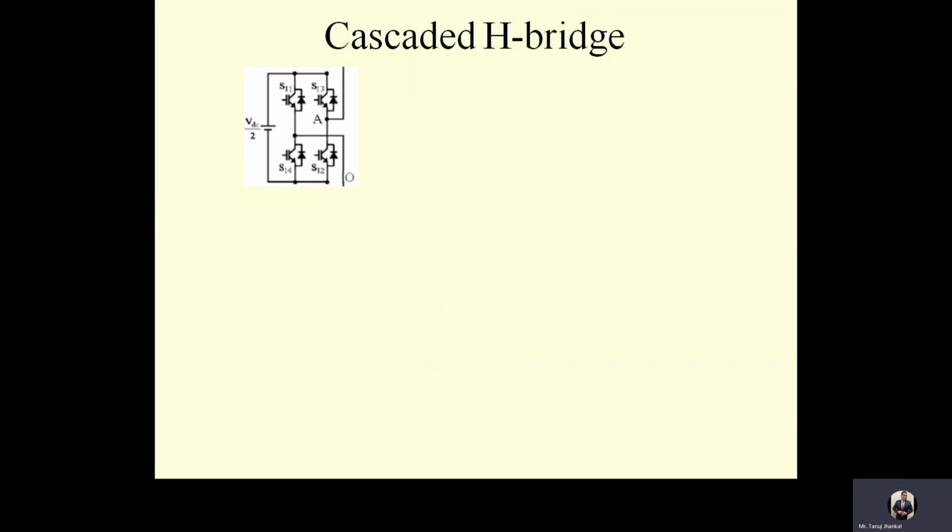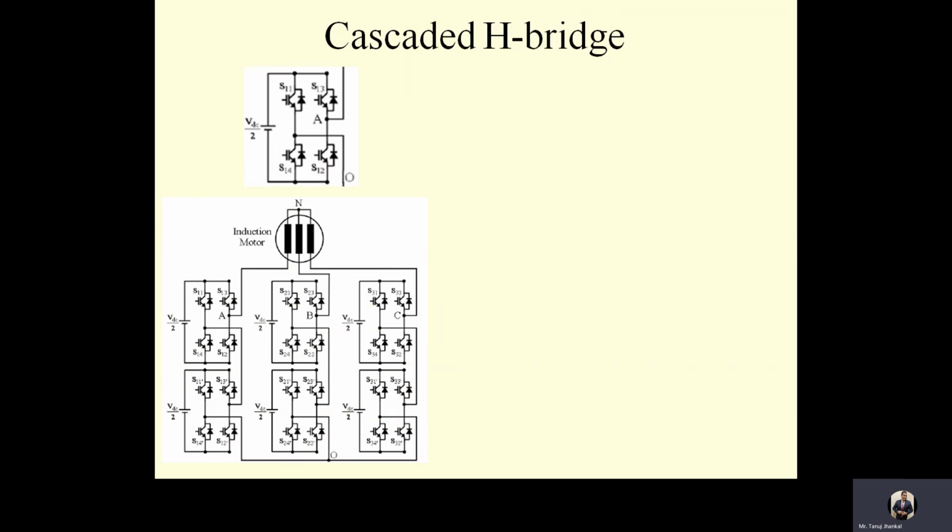As the figure shows, the cascaded multi-level inverter configuration consists of two cascaded cells for each phase, resulting in a 5-level inverter structure. Each cascaded cell consists of a full bridge inverter fed from an isolated rectifier.